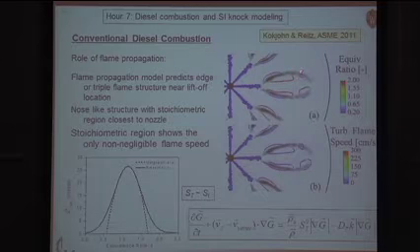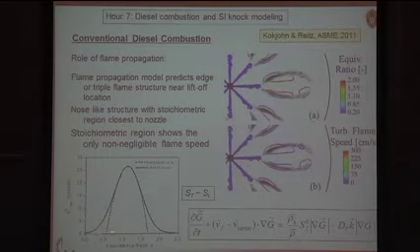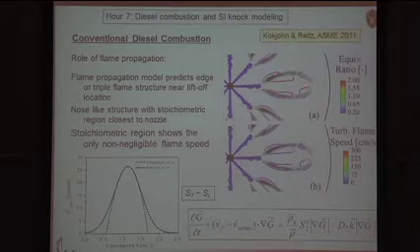The colors here show the equivalence ratio. So inside the jet, we have very rich mixture along the G equals 0 surface. If you look at the flame speed for very rich mixtures, it's 0. So basically, this mixture here, this G surface, is not moving. Similarly, on the other side of the flame, we have very lean mixtures, indicated by blue here on the G equals 0 surface.